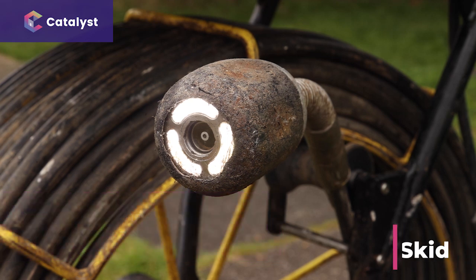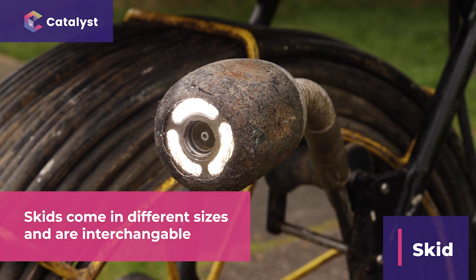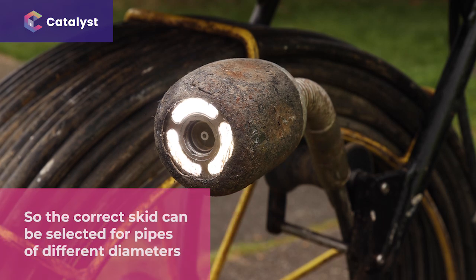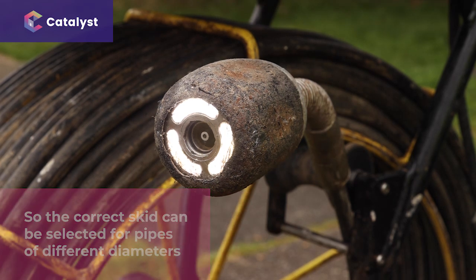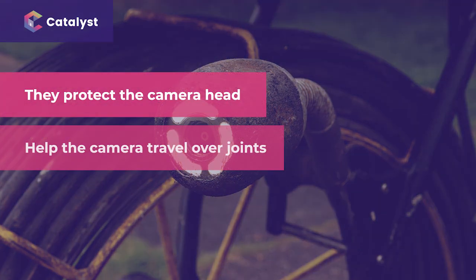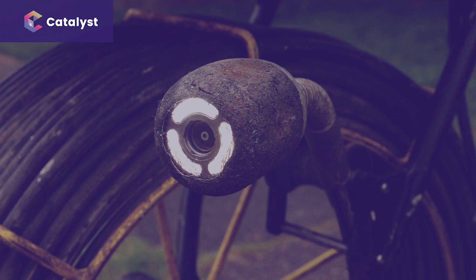Surrounding the camera head is a plastic shield called a skid. Skids come in different sizes and are interchangeable, so the correct skid can be selected for pipes of different diameters. Skids have 3 main functions. They protect the camera head. They also help the camera travel over joints by using the chamfer at the front and back of the skid. The skid also centres a camera in the drain. We'll go into more detail about the importance of centering the camera a little later.